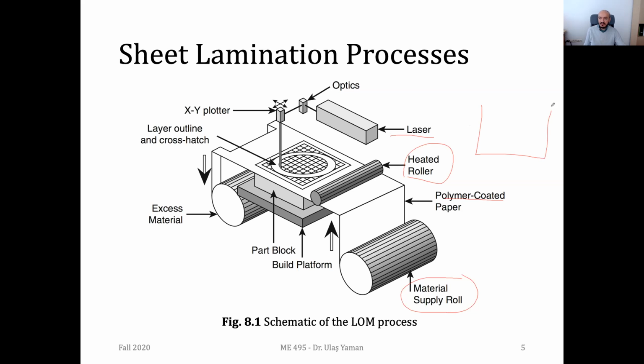So this is the top view of the slice. I think we have such a contour. So our laser is moving over this contour, and the remaining regions are simply divided into some grids. So right now they are squares, but in 3D, they will actually result in cubes, so that after the printing is over, they can simply be taken out of these regions, and you'll only be left with the part itself.